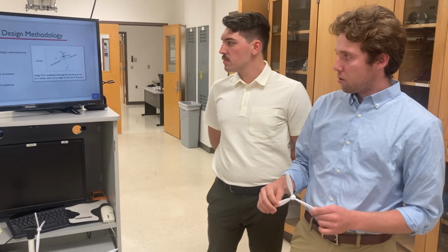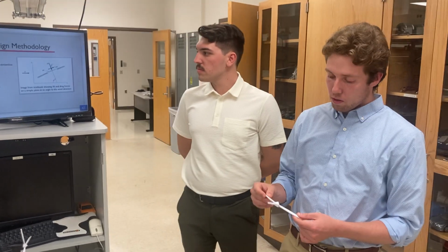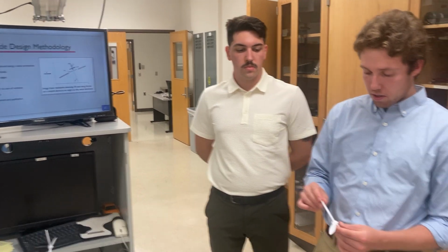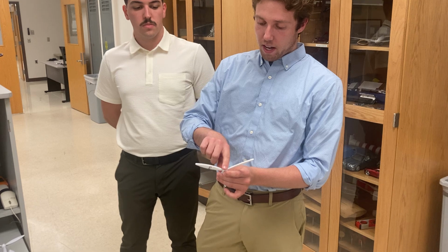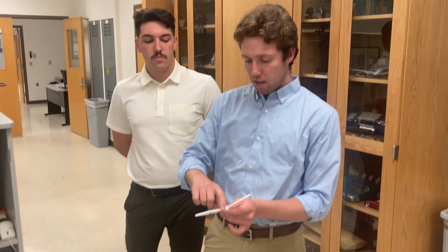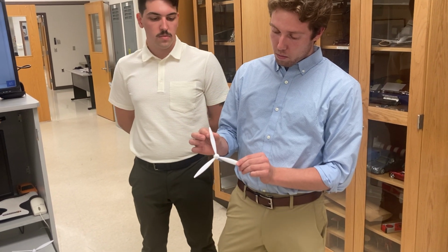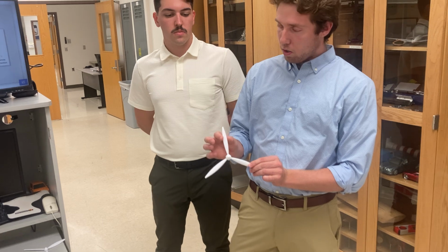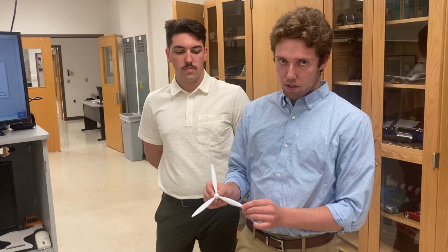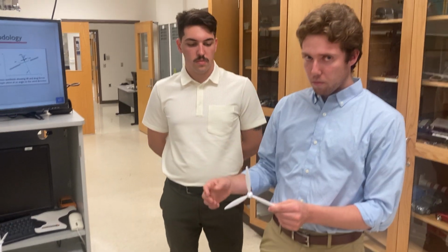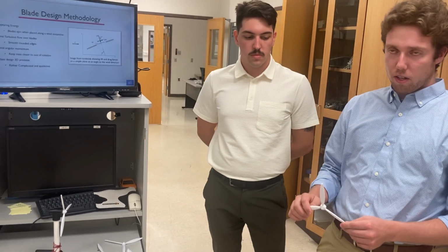So what we wanted to do was limit the turbulent flow over the blades, and how we did this was by smoothing out around the edges to make sure that the designs didn't have any blunt or flat ends on the leading edge or the trailing edge, and also limit the angular momentum by trying to bring the center of mass of the blades closer to the axis of rotation. And this would therefore make the blades easier to spin up as the wind velocity increased.